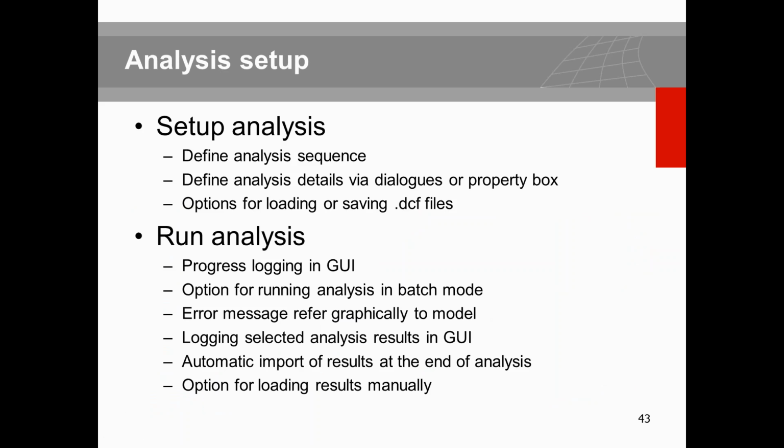The next step is setting up the analysis. Based on the corresponding dialog box, you can introduce a new analysis, then the corresponding analysis type, go through the settings of that, and indeed, you can always save these settings as a DCF, DIANA command file. That's one of the most common ones that we used to do. You can also recall your old command files, and after generating your model, you can save or export your model as a DAT file, and you can reload your DAT file even from the old version. So those are intact. You can still use the DAT and DCF files.